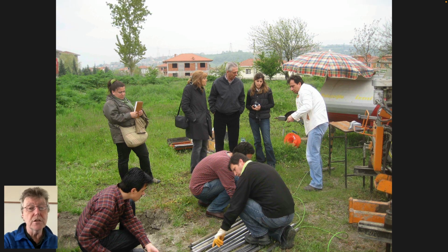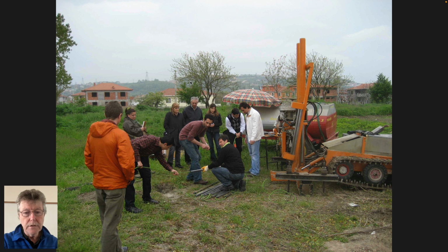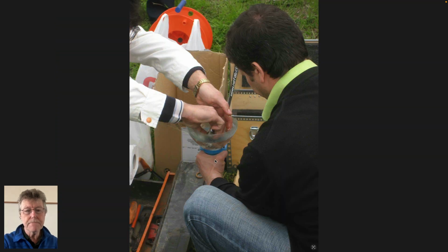You can use this to look at the liquefaction susceptibility of sands in an earthquake to be able to design mitigation methods. So this is the geoprobe. It's on a little truck. You can drive it into buildings. A stage goes up and down along these guides at constant rate to be able to push this in.